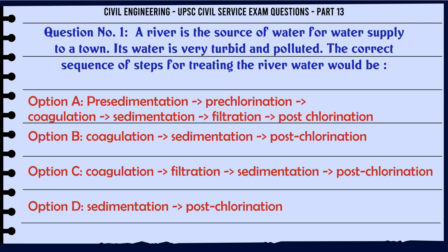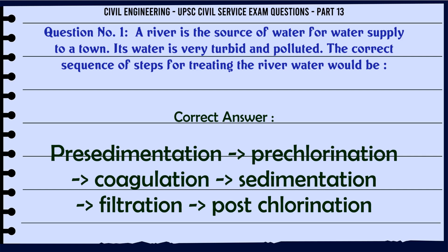B. Coagulation, sedimentation, post-chlorination. C. Coagulation, filtration, sedimentation, post-chlorination. D. Sedimentation, post-chlorination. The correct answer is pre-sedimentation, prechlorination, coagulation, sedimentation, filtration, post-chlorination.